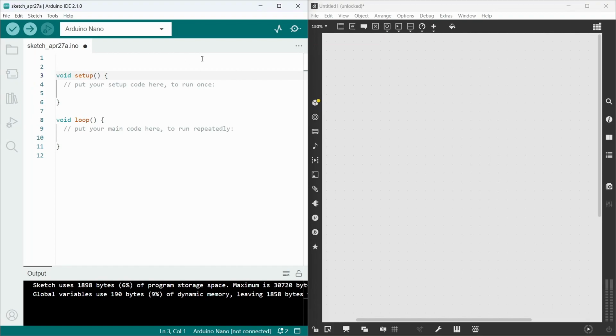So let's just get started, and what we're going to do is create a simple sketch in Arduino. As we're just sending single values today, rather than just sending the same value over and over again, I thought it'd be interesting to add a moving, changing value. So we're going to create a piece of code that counts from 1 to 20.